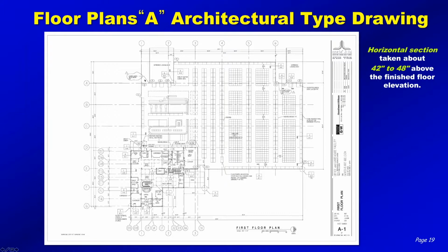Also, a nice thing to note is it also gives you all the column line identifications coming across the top. One set of them will always be numbers. The other set of those identifications will be letters. And you'll note there'll also be some offsets, like down here, 0.5. So we have column line 1 and there's something off a little bit to the left of it. So they're making that 0.8 or 0.5. Here we have 1 and then 1.3.